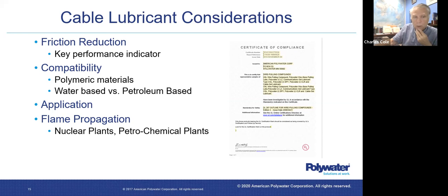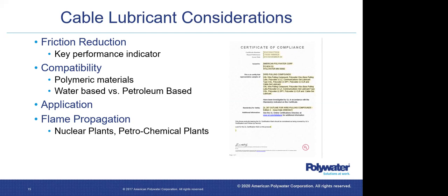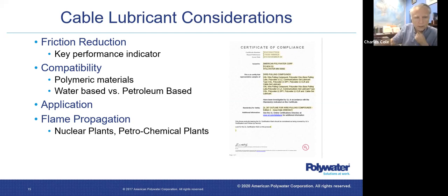Polywater's lubricants are all water-based, so they're not going to have any compatibility issues with a vast majority of the cable jacket types and duct materials that they'll run into. Application is just the ease with which you can install or apply lubricant. You saw that the people in the Karnataka situation were applying lubricant by hand.